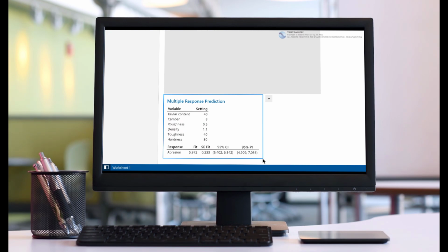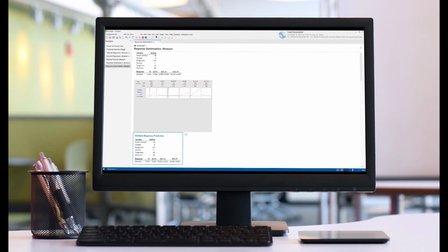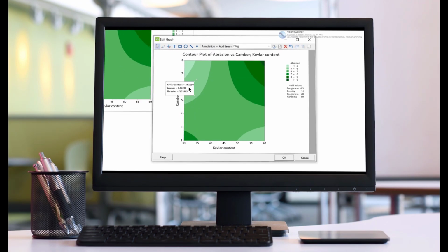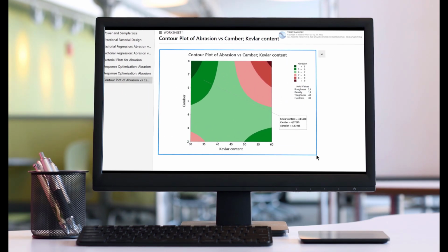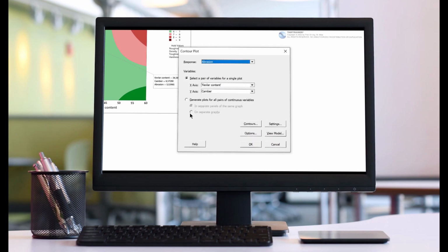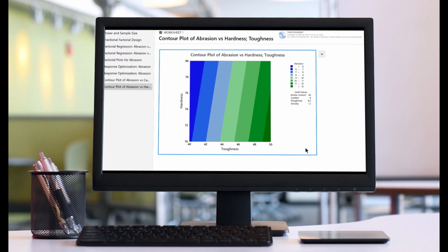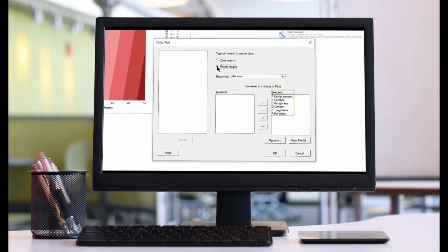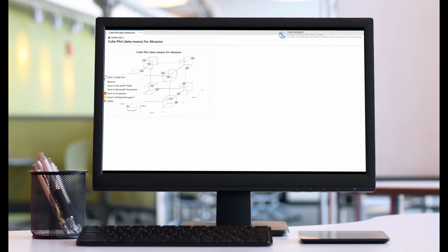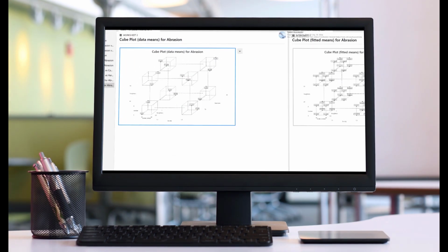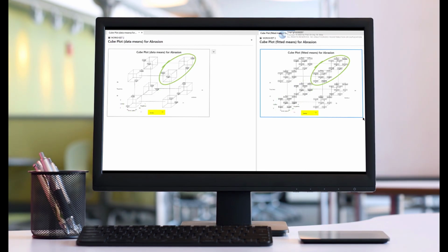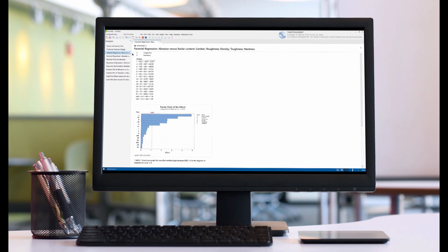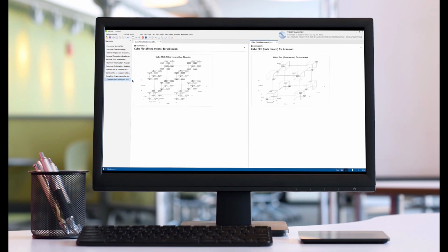In the third and final part of our Minitab tutorial, we will then use the final optimized DOE model to enter the response optimization phase in order to determine the optimum parameter settings, to reduce abrasion on the skateboard wheels to a minimum. In this context, we will also look at the corresponding interaction diagrams. Once we have determined the optimum parameter settings by using the response optimization, we will then define specific working ranges for the parameter settings. For this purpose, we will get to know the useful display forms of contour plot and cube plot, actively create and interpret them in order to define the permissible tolerance ranges for our parameter settings, so that, for example, the required target value in our response variable is still achieved even with unexpected process instabilities.